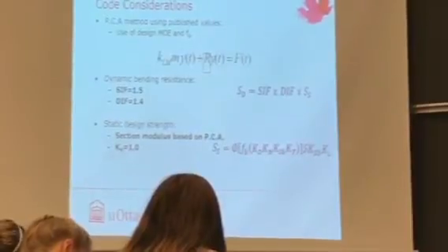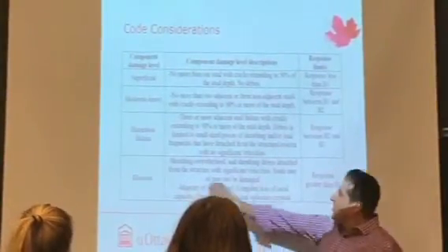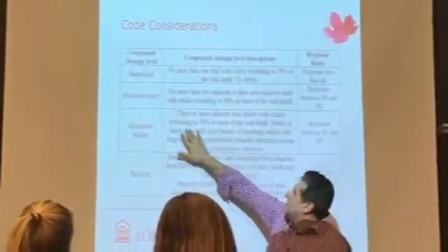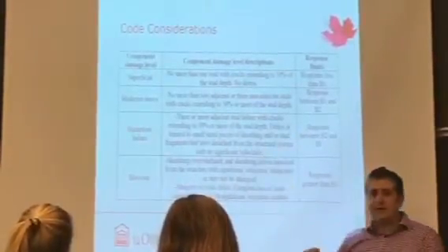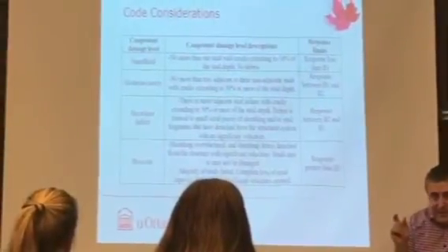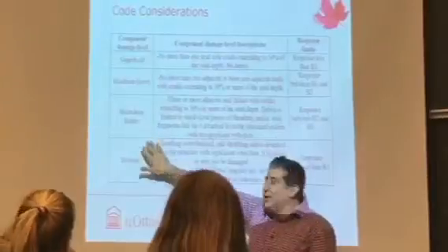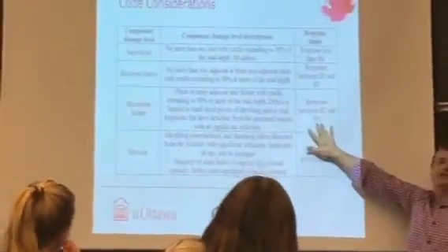I can show you an example of what the code says. The code says, if we're talking about hazardous failure, it means 3 or more adjacent stud failures with cracks extending 50% or more of the stud depth, debris limited to small size. So it tells you that at that displacement, we call it hazardous failure. This is the description of it, and in terms of response, it lies between B2 and B3. I'll come back to this.